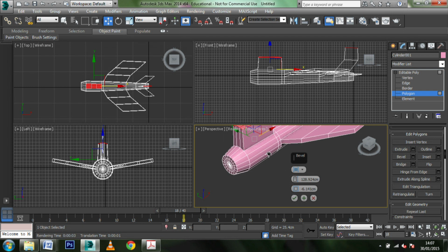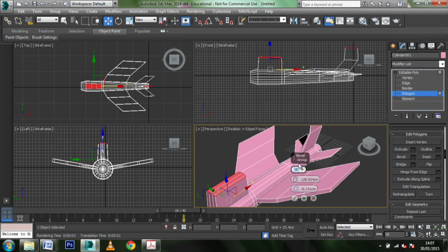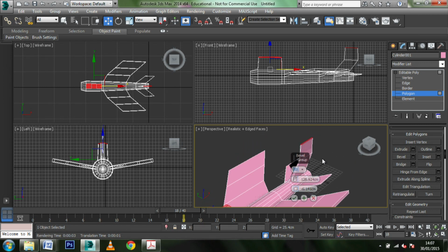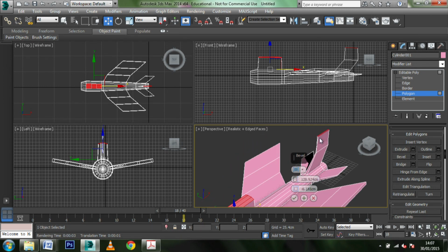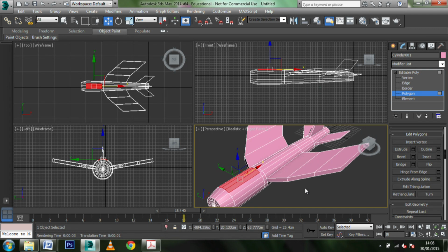and what this has done is created a new piece of geometry which is in the same settings as we used in the tailplane. And you can see I've accidentally here had the tailplane selected at the same time, so I'm just going to cross this off, click away into space, and then I'm going to select those 3 polygons again. There we go. Select the bevel tool, and I bring this down, and I can also tighten up the top there as well.